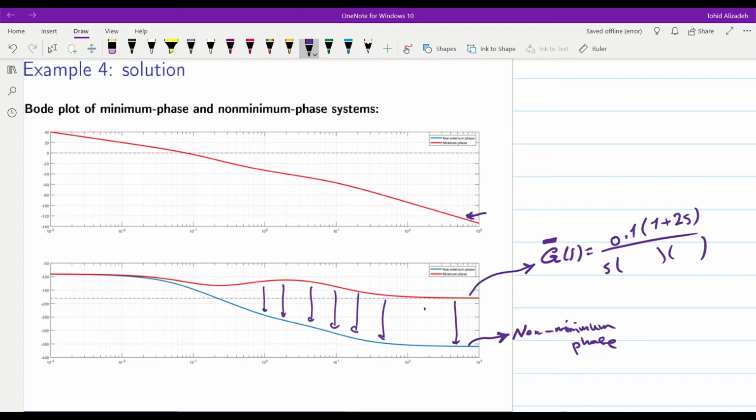If you consider the absolute value, you can see why this is called the minimum phase system, because its phase is smaller than the non-minimum phase system. So you see that at the point in which a 0 is located on the right half plane at omega equal to 0.5, which is this frequency, the slope of the phase, where the phase goes down, gets worse.